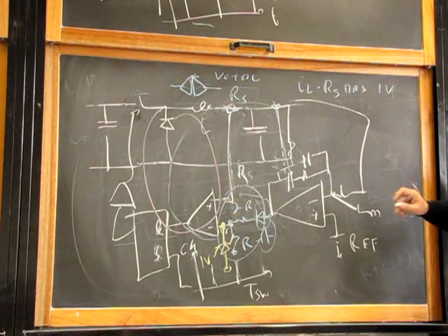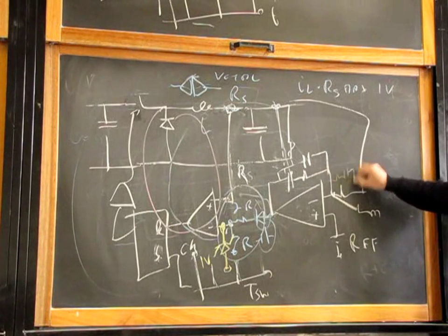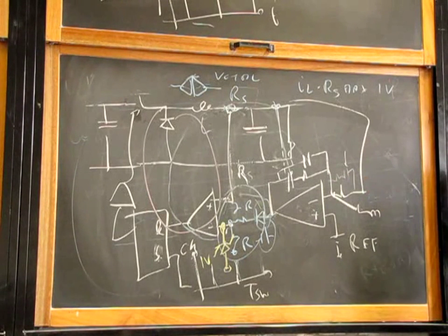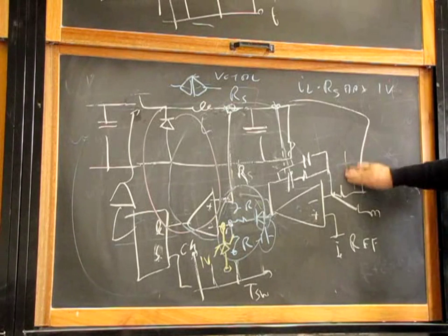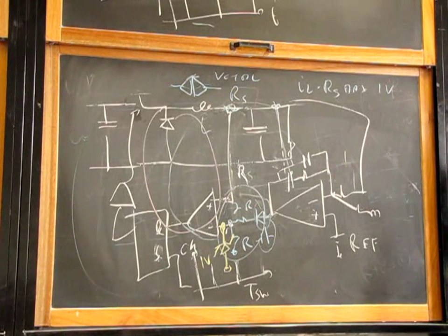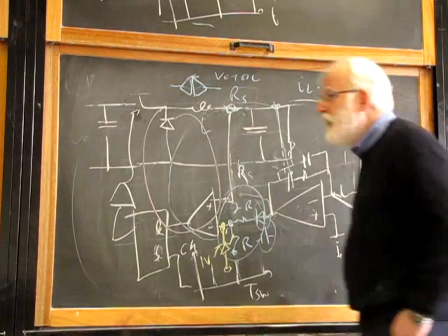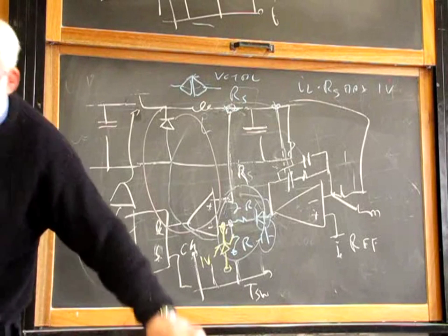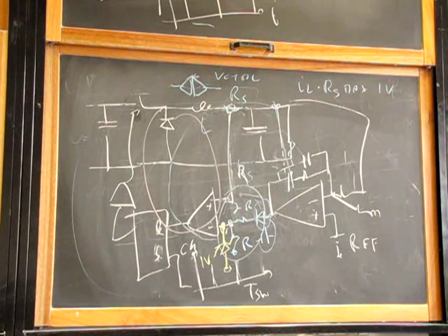If you have a type 3 compensator, that is, you have one extra RC, this capacitor is critical for the saturation, the one that makes more damage. So if you don't have it, it's faster to recover from saturation. Not only, there is one extra advantage, at least one extra advantage, then there are more.